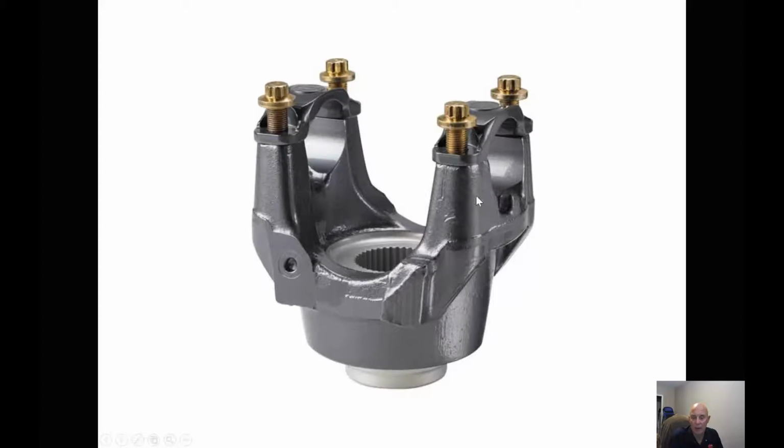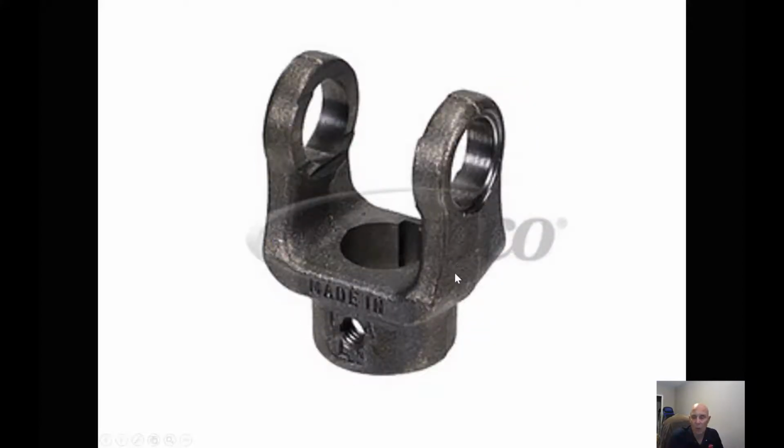When we're dealing with half rounds, these straps should be replaced. These also have to be torqued up. So make sure we torque them properly, and make sure that the caps fit inside here properly. On a full round, we want to make sure that this is clean and the caps fit in there nice and smooth beforehand, so that when we go to assemble it, it's not going to be tight. And if we've already checked to make sure that these slide in and out, and we go to assemble it and it's tight, we have a problem with the yoke being spread.